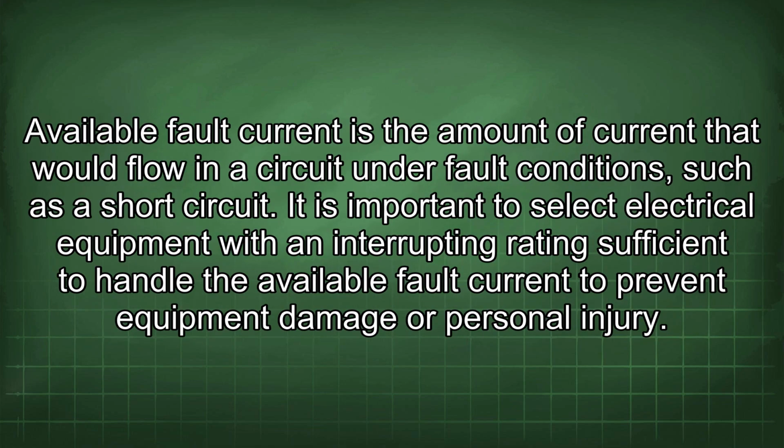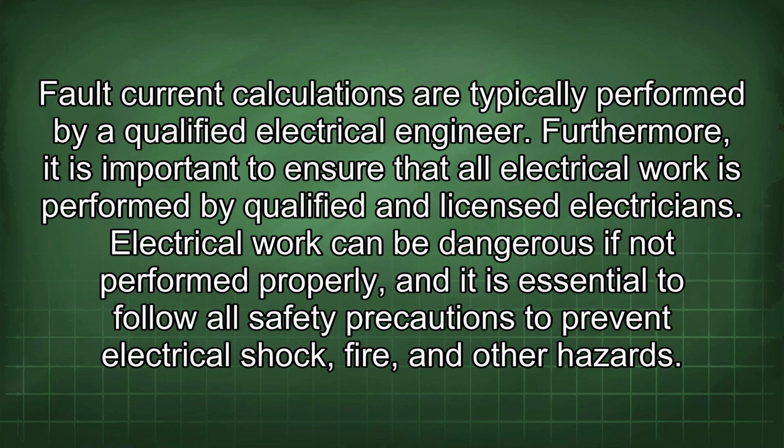Available fault current is the amount of current that would flow in a circuit under fault conditions, such as a short circuit. It is important to select electrical equipment with an interrupting rating sufficient to handle the available fault current to prevent equipment damage or personal injury. Fault current calculations are typically performed by a qualified electrical engineer.